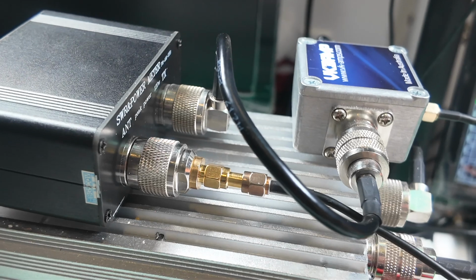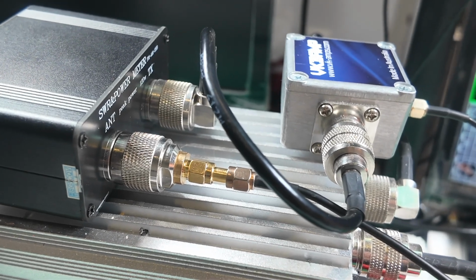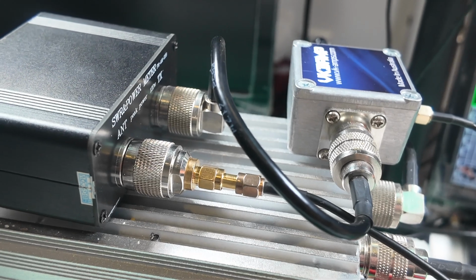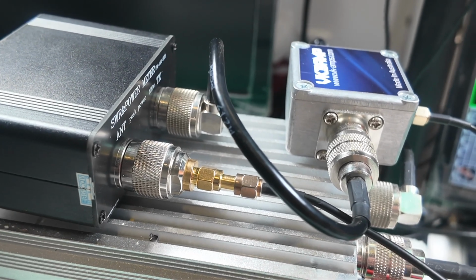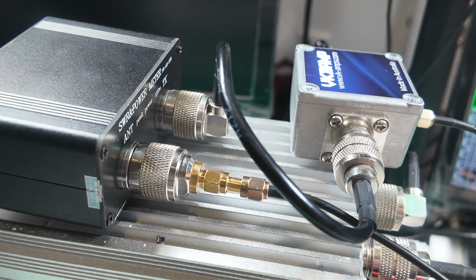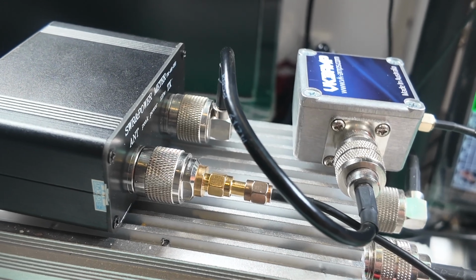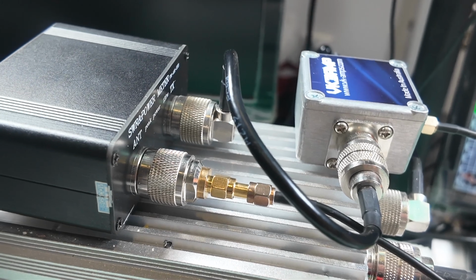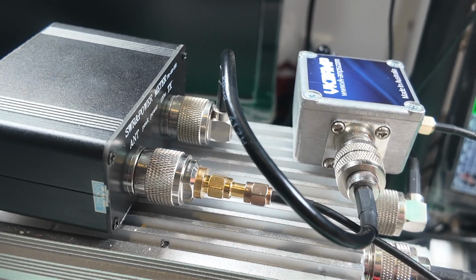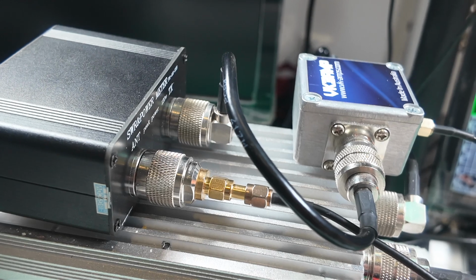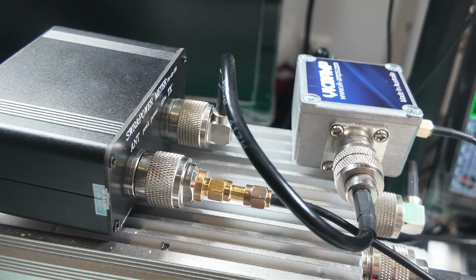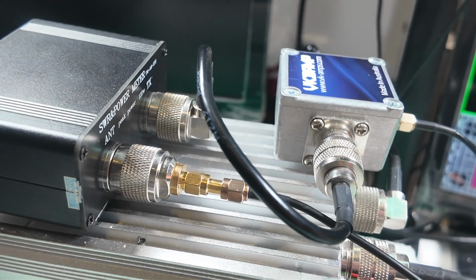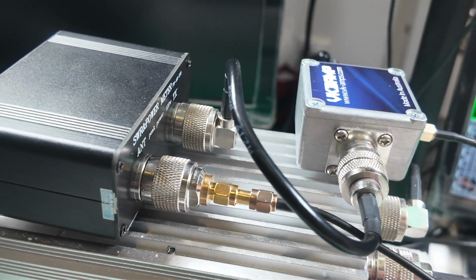In other words, we're pre-distorting something that is not right to make it right. So we're adding a pre-distorted input to the output, so when it goes through the amplifier, it will modify the output with the pre-distortion, so the output will be more linear, or, you know, as we expected.